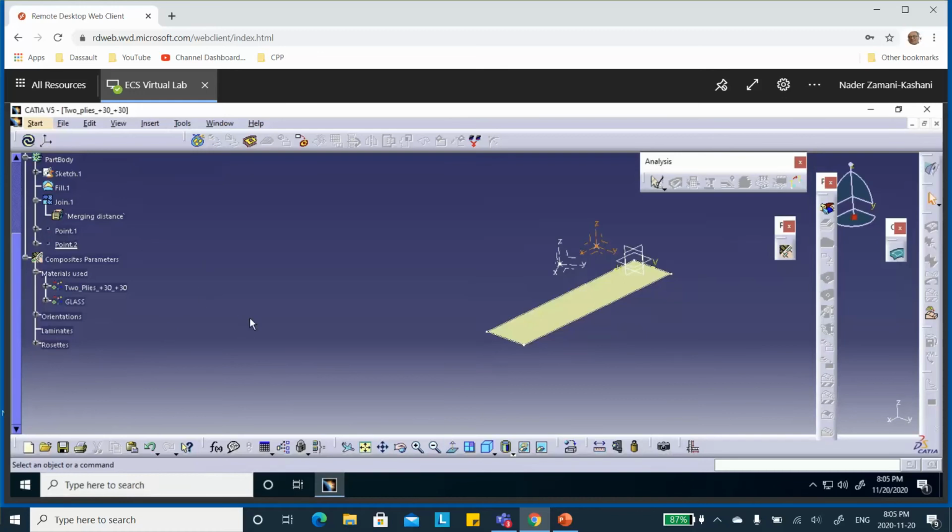Now in the second tutorial with a single ply, I did this thing with the ply method, okay? Manual ply method, manual ply. When the problem becomes complicated, for example, there are several areas that are laminates stacked on top of each other, it may be better to do a different method called the zone method, but this is simple enough. We're going to do manual ply. So the first thing I need to do is to create a ply group.